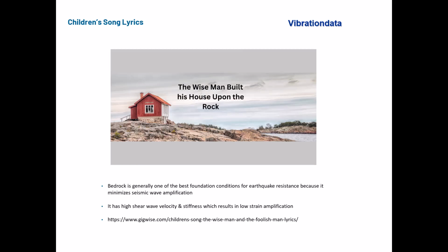So bedrock is what we want to build upon, because it provides earthquake resistance in terms of minimizing seismic wave amplification. It has a high shear wave velocity, the bedrock does, and stiffness, resulting in low strain amplification. So it's a good idea to build your house upon the bedrock, and as the song goes, the foolish man built his house upon the sand.